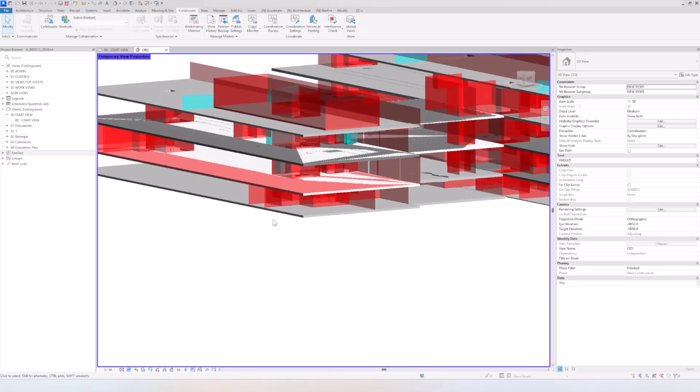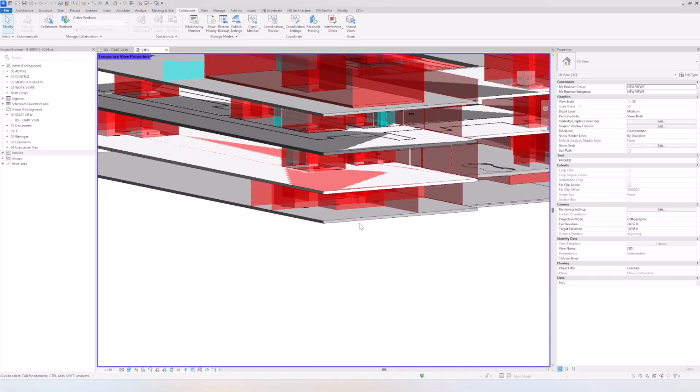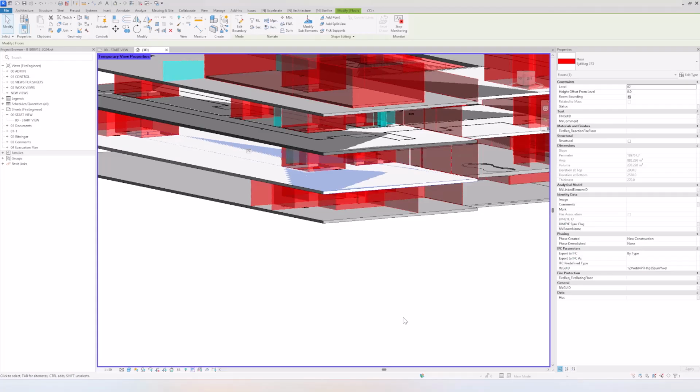As you can see, how it looks right now is kind of shifting in colors. This is not a good look. So what I usually do is I adjust this so it kind of looks good for everyone, not only me. So we don't want to use view filters. That is kind of the last solution if we don't know really what we want to do or how to do something. So what I'm going to do is we can select one or several slabs, and we can go into height offset from level. And here we can go and write -1.